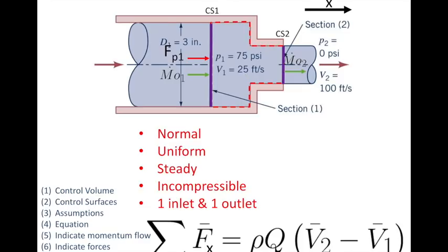So we've got some force due to the nozzle acting on our control volume. The direction here is probably a little bit obvious, a little bit intuitive, but this is an example where it's not always clear which direction that force might be acting. So as I suggested on the last problem, if you're not entirely clear which way it's acting, draw it to the right and then see how it comes out.